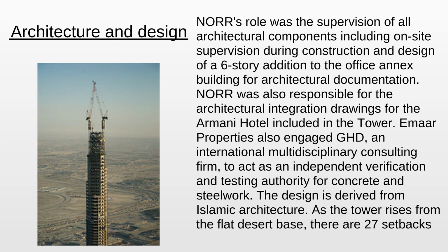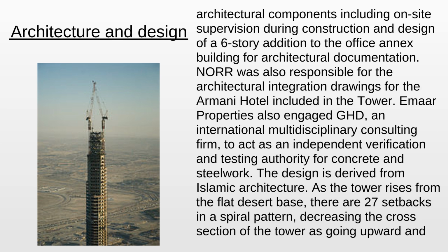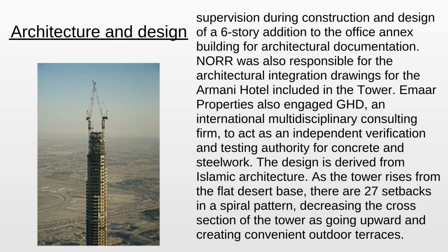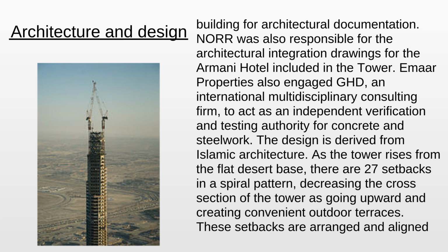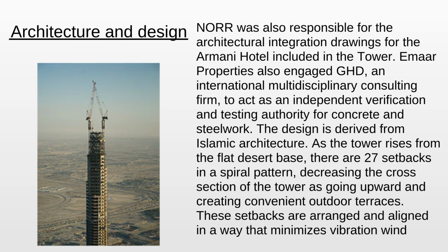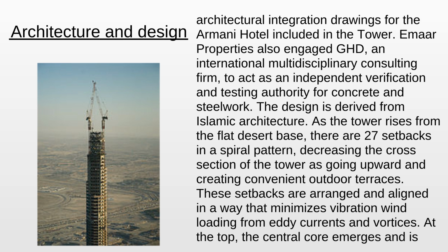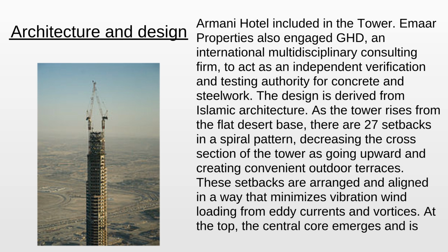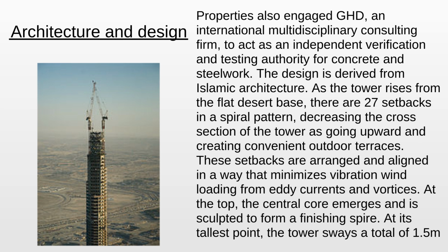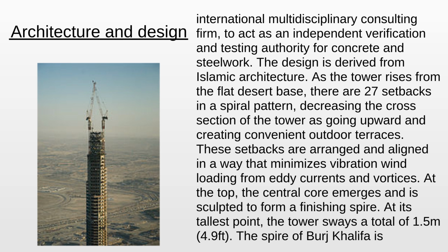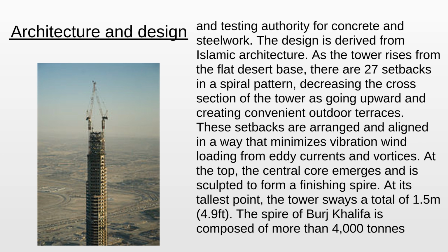Emaar Properties also engaged GHD, an international multidisciplinary consulting firm, to act as an independent verification and testing authority for concrete and steelwork. The design is derived from Islamic architecture. As the tower rises from the flat desert base, there are 27 setbacks in a spiral pattern, decreasing the cross-section of the tower as going upward and creating convenient outdoor terraces. These setbacks are arranged and aligned in a way that minimizes vibration wind loading from eddy currents and vortices.